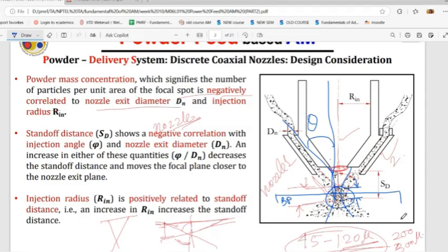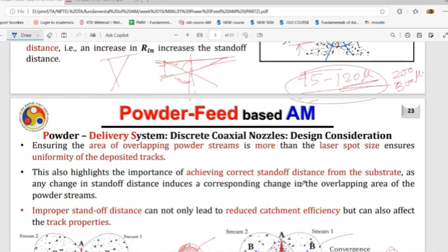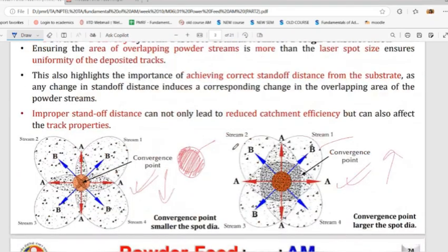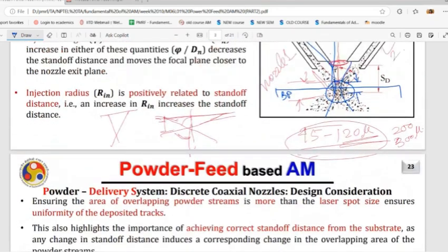If the angle is very steep, then also it can come. But if it's nearby 45 degrees or so, then you need to have forceful argon gas to carry the powder. It will not come automatically out of gravity. So that is the fundamental thing, and that's why it's important to choose the angle.